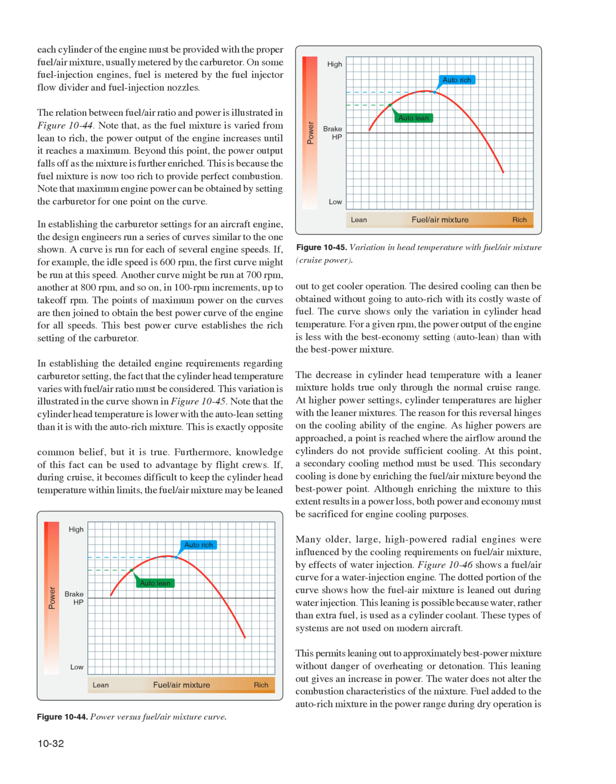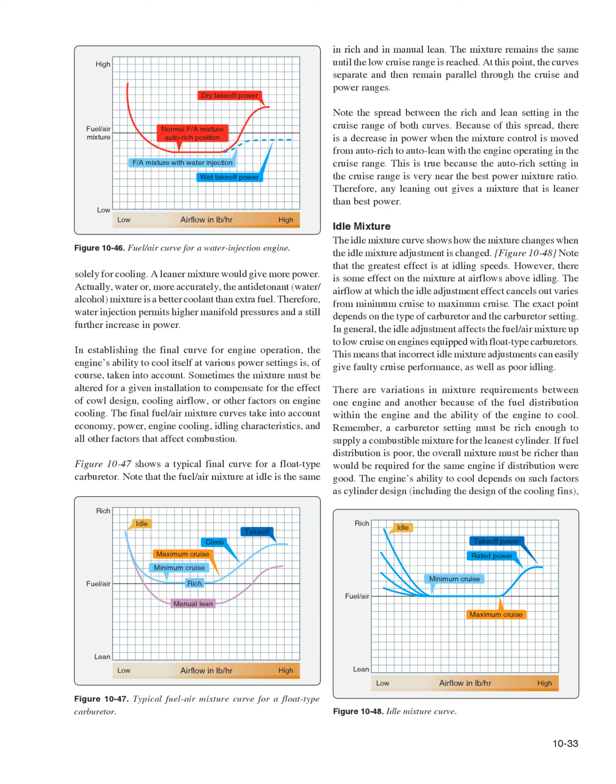The water does not alter the combustion characteristics of the mixture. Fuel added to the auto-rich mixture in the power range during dry operation is solely for cooling. A leaner mixture would give more power. Actually, water or, more accurately, the antidetonant water/alcohol mixture is a better coolant than extra fuel. Therefore, water injection permits higher manifold pressures and a still further increase in power.